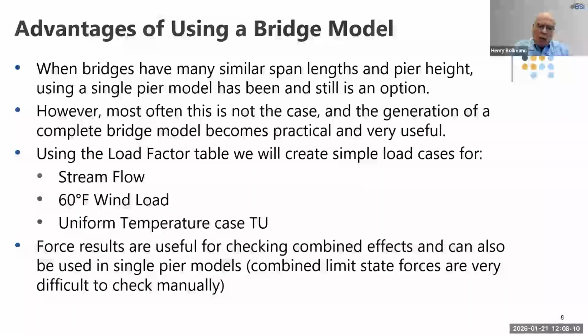We're going to show how we can edit the load factor table in FB-MultiPier to create simple load cases. In this case, I'm just going to do stream flow, wind, and temperature. The reason I'm doing that is for several reasons. One of them is because when you take advantage of the bridge model and you can calculate these forces, you can transfer those to a single pier model, if you like, and then proceed with a single pier model like you're always, maybe, used to using. But the bridge model allows you to do this.